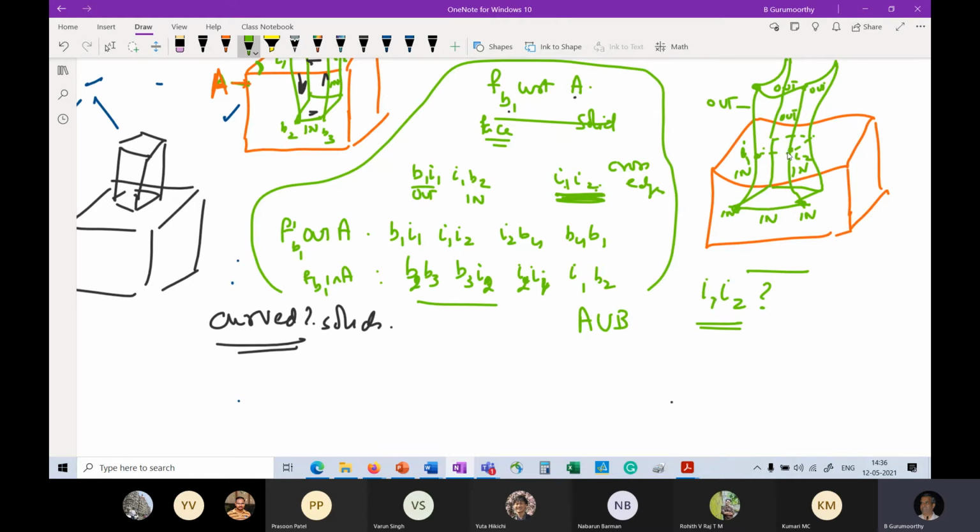And to find that equation, I actually have to do an intersection of this curved face F1 and this curved face FA1. So unless I do this intersection, FA1 intersects FB1, I cannot get this. Unlike the linear case. But other than that, everything remains the same. So this is the only additional complication when you're dealing with curved objects: while you can get the topology or the connectivity of the object from this process, the geometry will have to come from actual intersection.